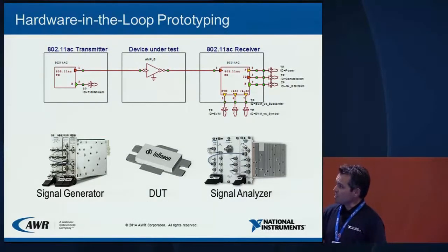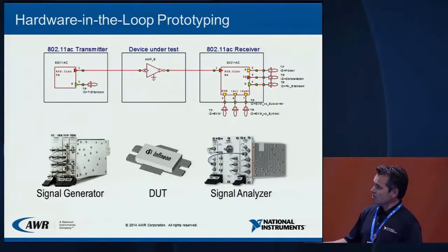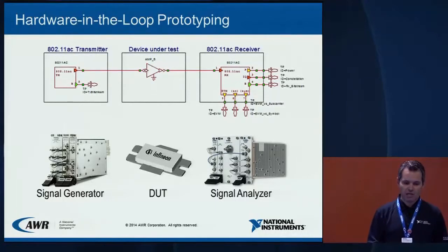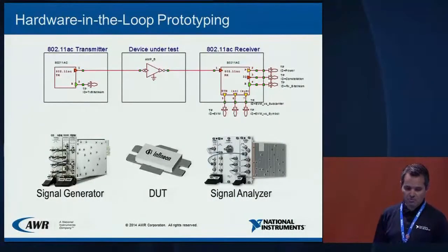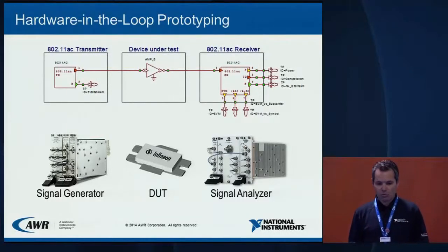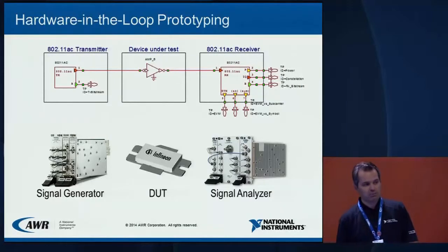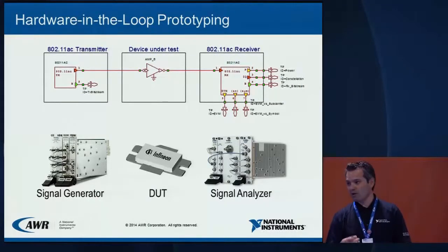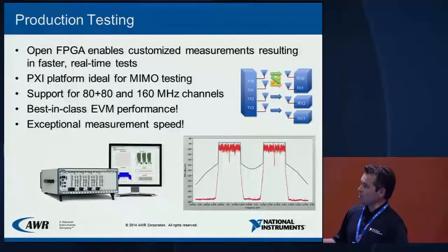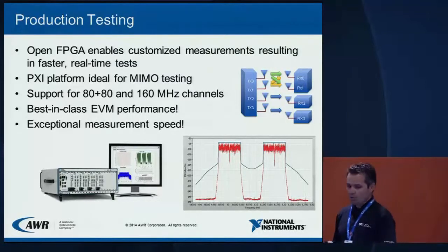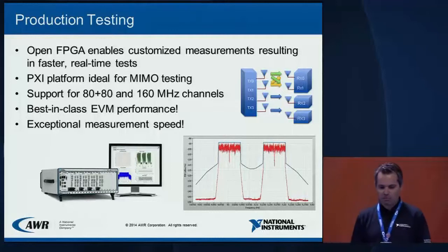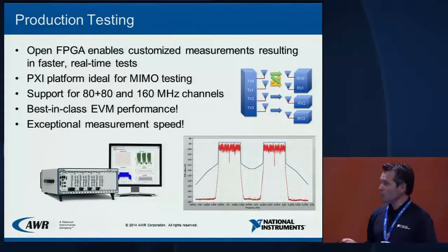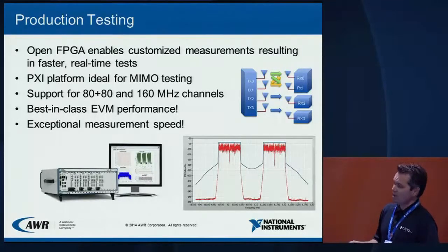And as I mentioned, the next stage would be replicating the same design process by taking advantage of the tight connection between VSS, LabVIEW, and the NI hardware, so we can replicate the same test bench, but in this case we include the RF components that we want to measure. What's important is that we are still using the same test bench, the same measurements, so we are not redeveloping the test bench every time we move down the design process. And furthermore, when we move down to production testing, we've been able to take advantage of the FPGA capabilities of the NI platform that we can use for customizing measurements and realizing faster real-time tests.